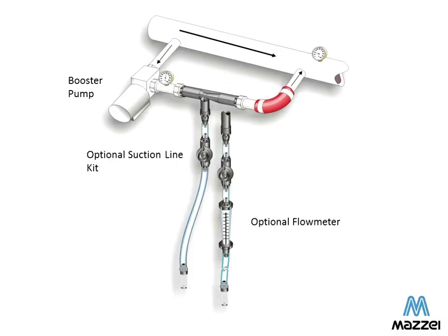The booster pump method. This is helpful when you cannot afford a pressure loss in your main line. You don't have the capability to reduce your pressure. So what we do here is we take a small portion of the main flow, boost the pressure of that water, and provide that to the inlet of the injector. So now the inlet of the injector sees the higher pressure water from the booster pump, and the outlet of the injector will see the main line pressure.